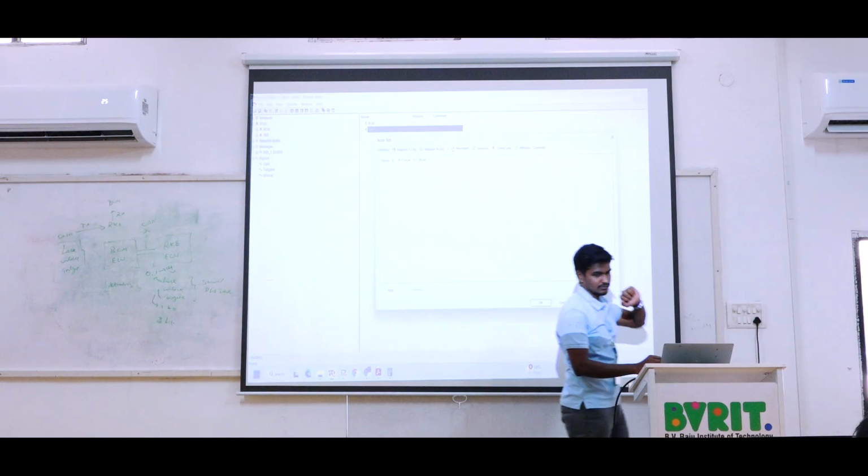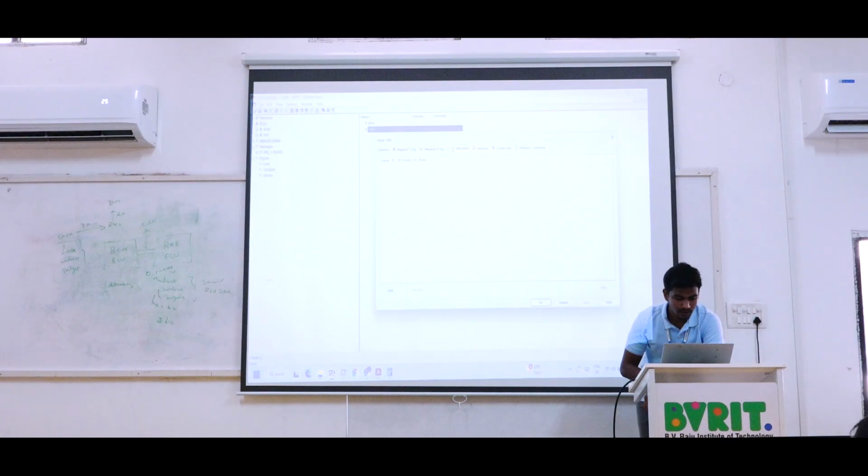TX messages. Okay. So for these TX messages, just click add. Add means the messages you have created in the message column will be shown. Then you just click OK. Now the messages are added: message ID number 400, in standard format.